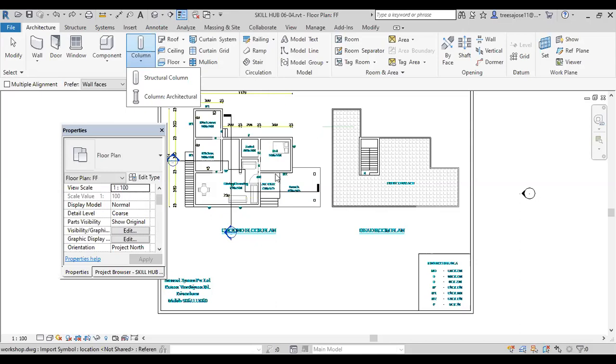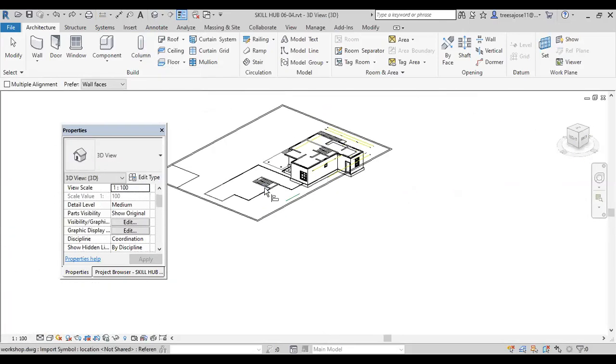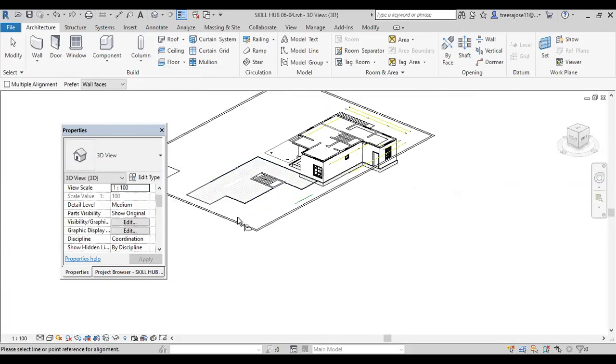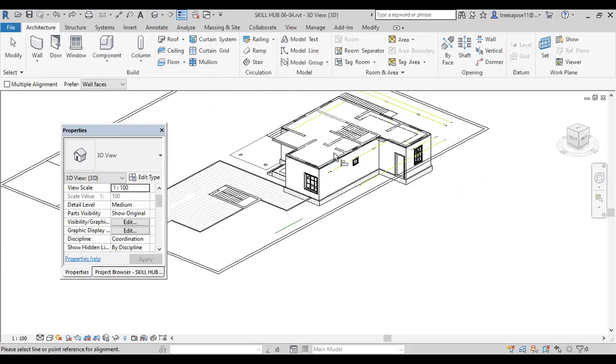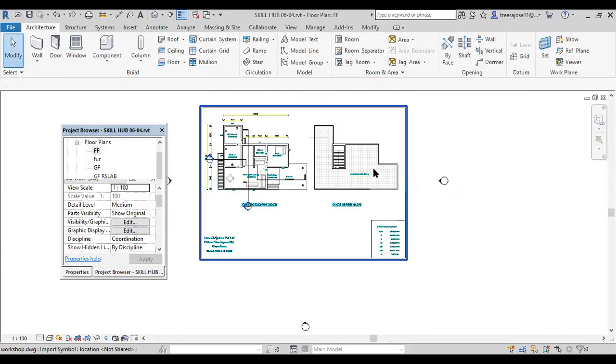If I create something, okay, this is my first floor. Clear. I have already placed and finished this ground floor, and I want to draw the first floor. If I select this and make it the first floor, automatically the model will come here only. Actually, I need this reference here so that you activate it. This is the procedure, so that you activate the first floor.